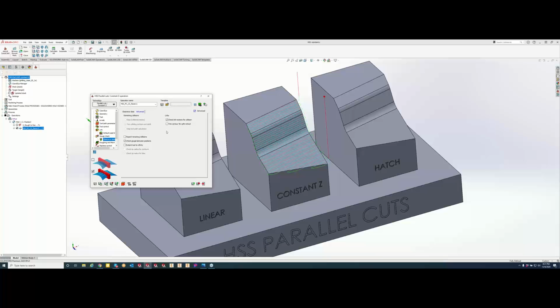Yep. The extend tool to infinity I've used in the past, just because you'll get into situations where the tool definition is a little bit short. And so if you have something that is on a bit of an overhang, if that tool is not defined tall enough, you could run into a potential gouge. But by checking the extend tool to infinity, it eliminates that. So there are good options in here. It's just the circumstances are going to be rare. But they are nice to have.